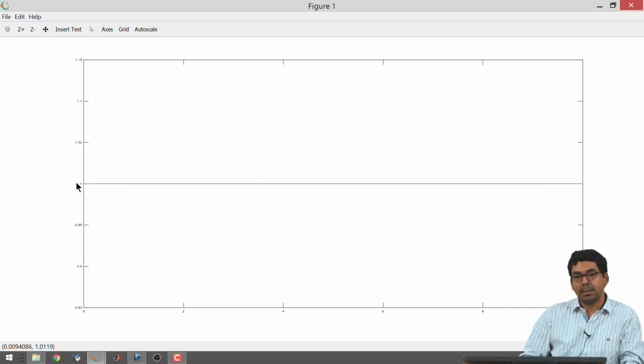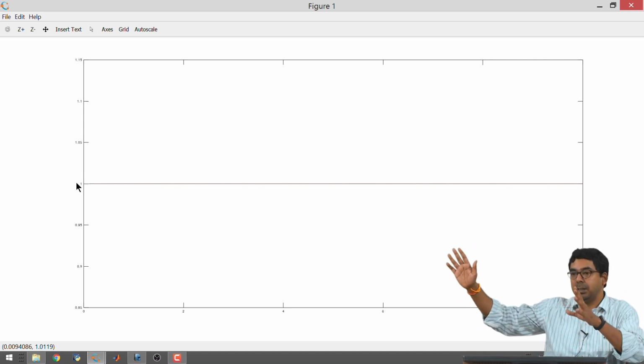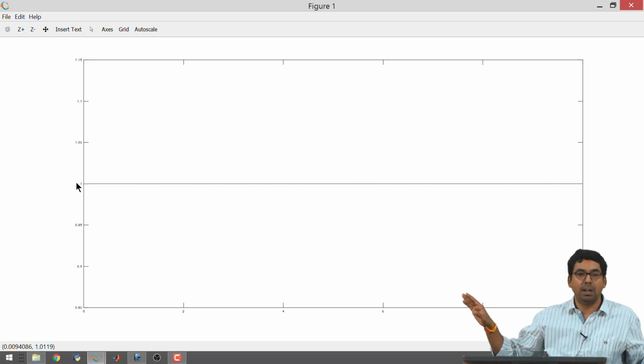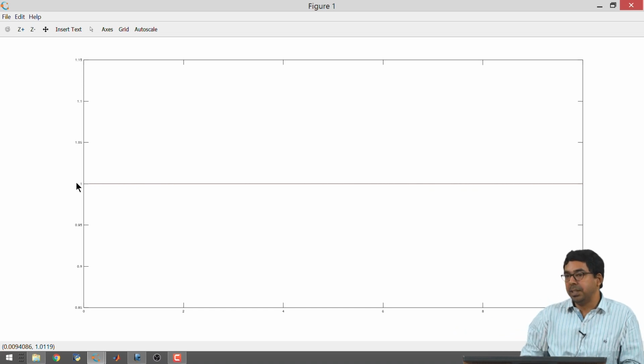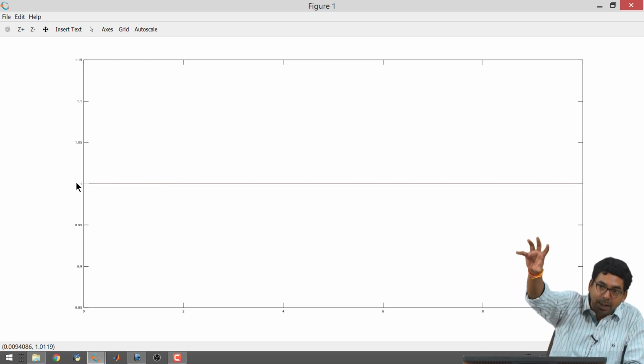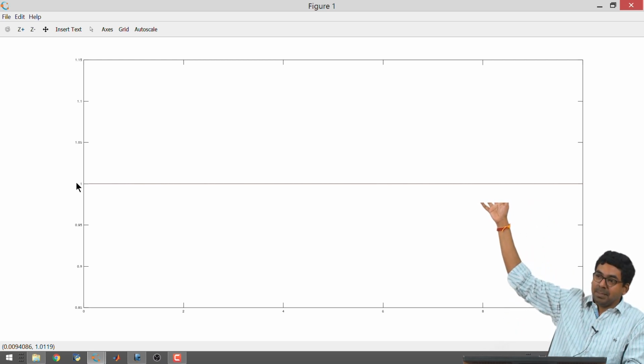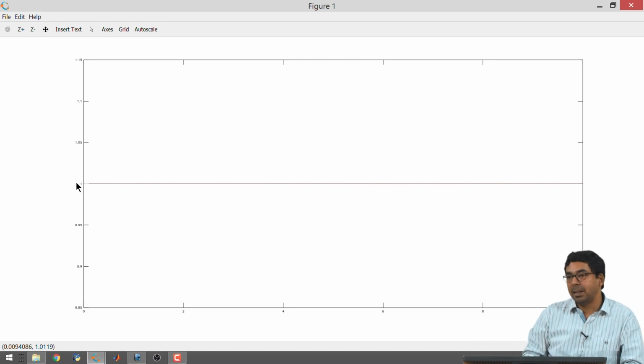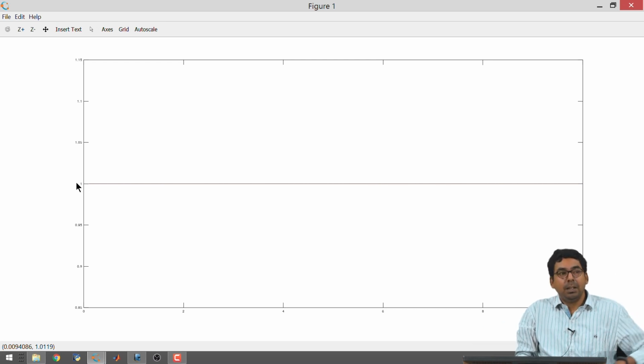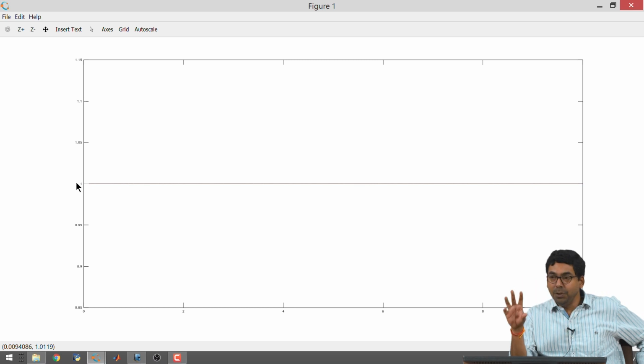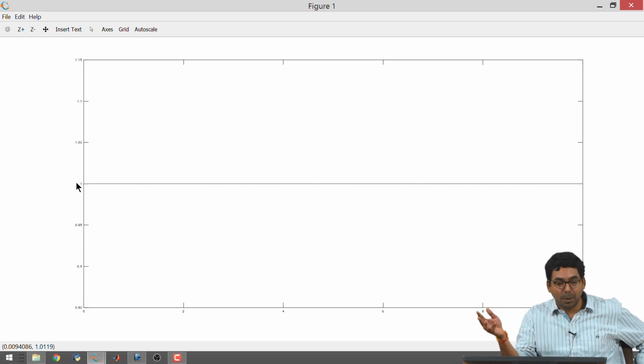In this particular case, you are launching a plane wave and you are keeping a waveguide, and the waveguide has no effect on the plane wave because it is traveling as it would in a homogeneous medium with a constant velocity. So, whether you had kept the waveguide or not, the phase and the group velocities will be the same as air. Secondly, whether you kept the waveguide or removed it, there is going to be no dispersion.